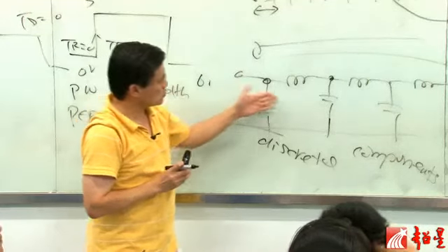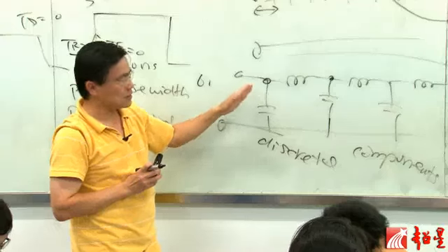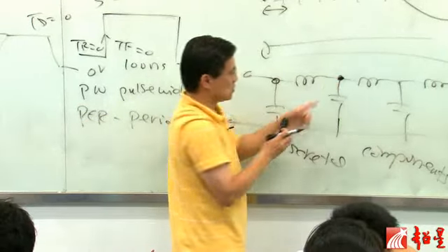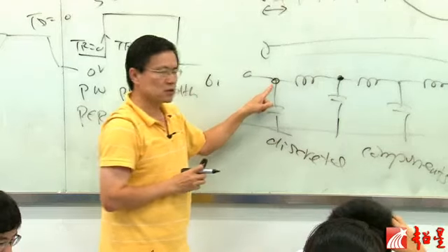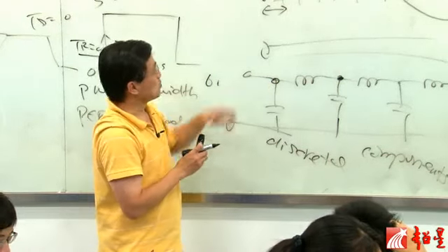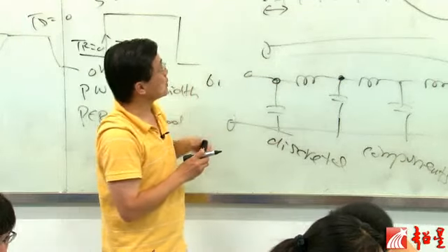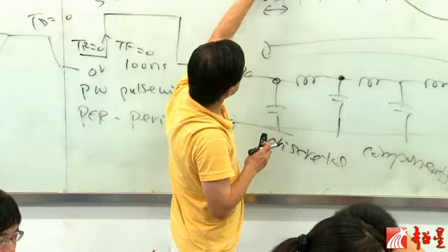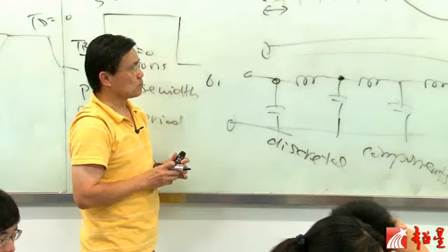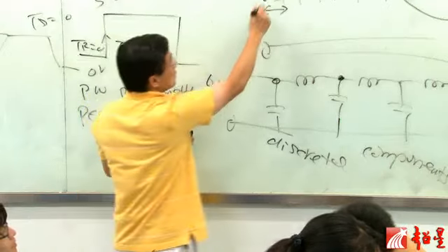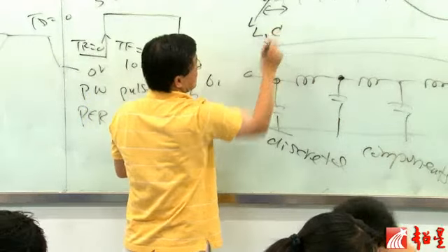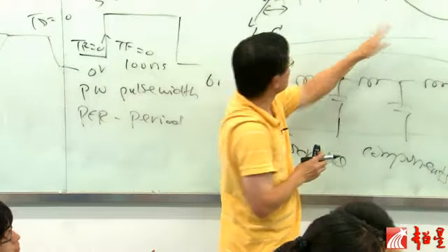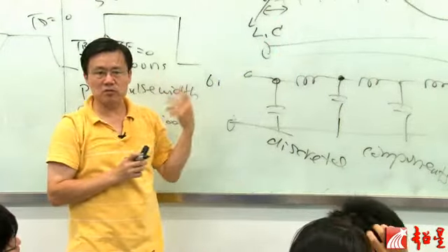That's the underlying assumption, because at this point the voltage is a single voltage, and at this point the voltage is a single voltage. This is a physical transmission line, but if you divide it small enough, the voltage within each piece is more or less the same. Each piece is 1 LC, so you need 10 pairs of LC to approximate this transmission line.